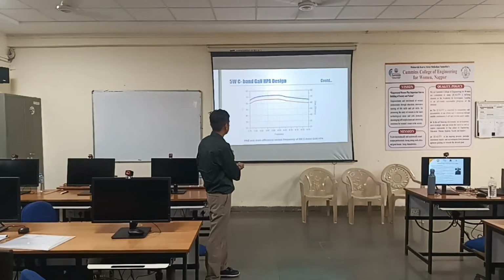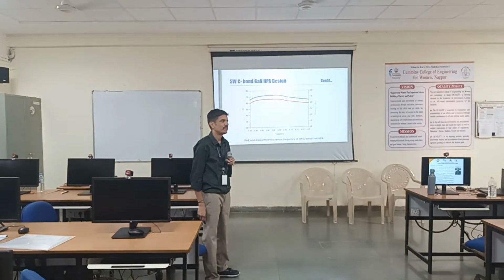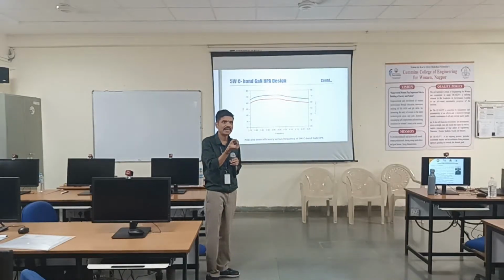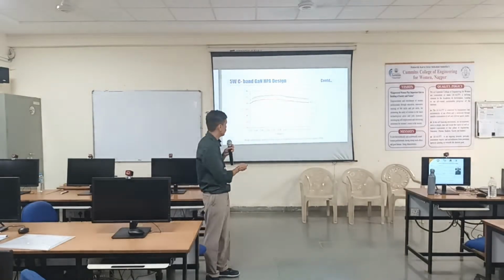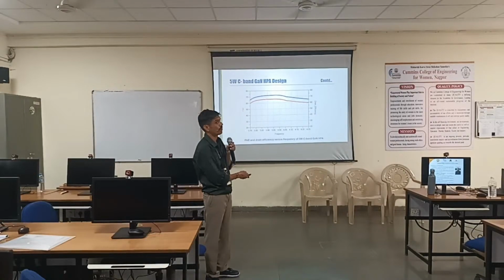You can see more than 60%. PAE we could achieve more than 60% for the band of 500 megahertz, which was the challenge for the Ku band design. Even for 100 megahertz, we could not meet the requirement of PAE 50%. Here we could very comfortably meet the PAE more than 60% throughout the band of 500 megahertz.